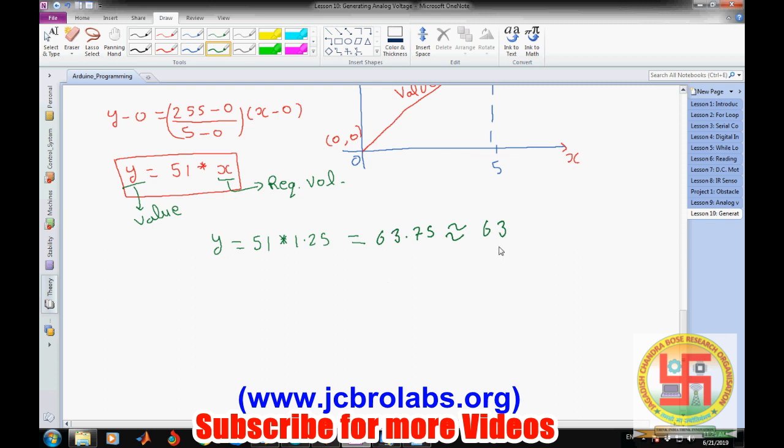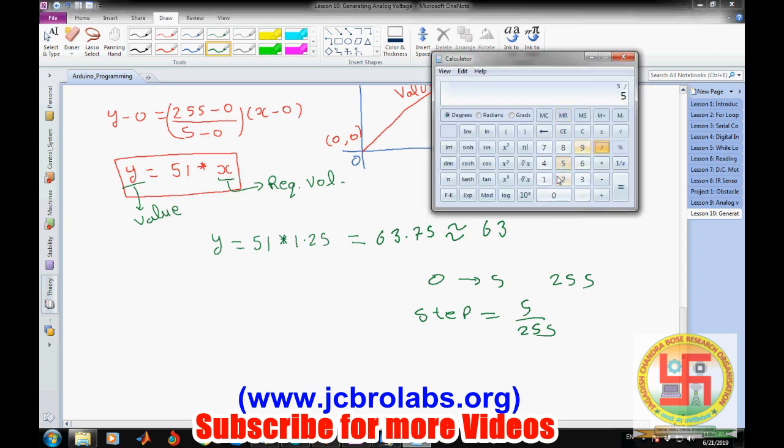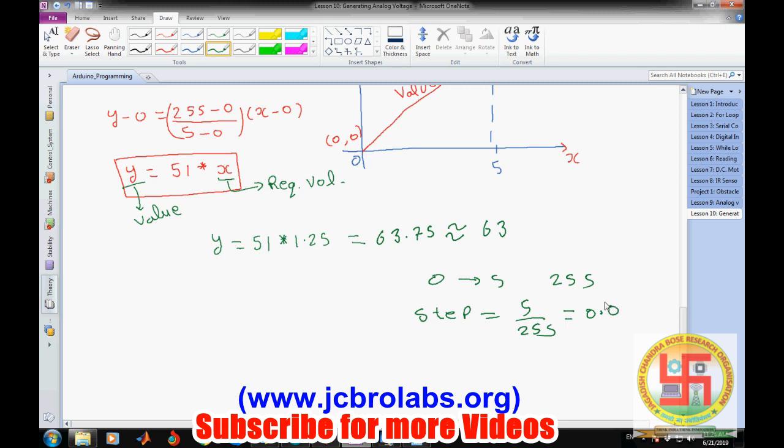Now we can also find the resolution, or at what step we can generate this value. Because for this 0 to 5 range there are 255 steps, our step size is simply 5 divided by 255, that is 0.019 volt. So at this difference, the values will be generated.